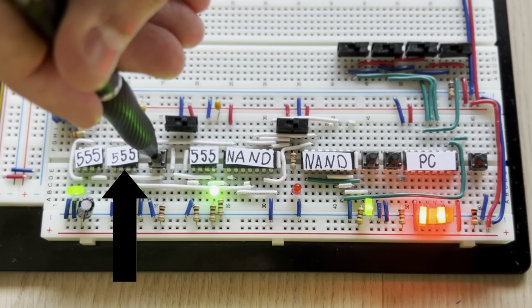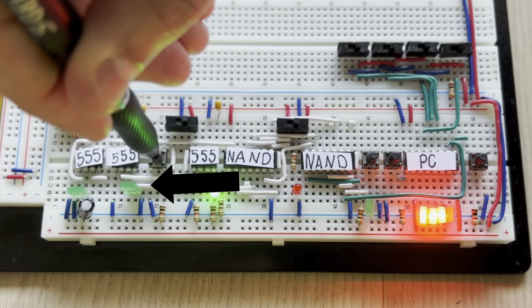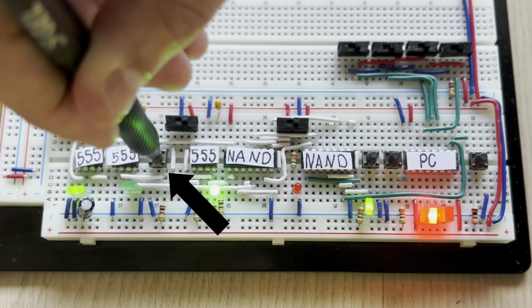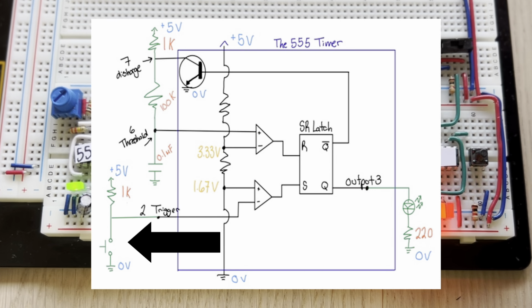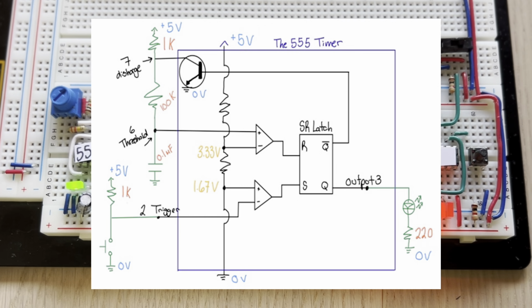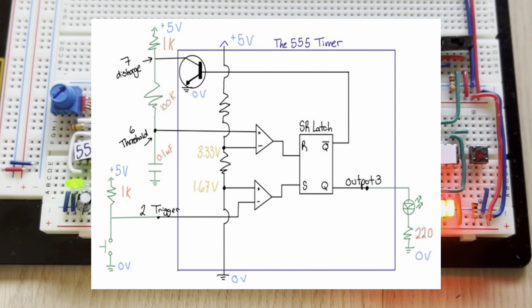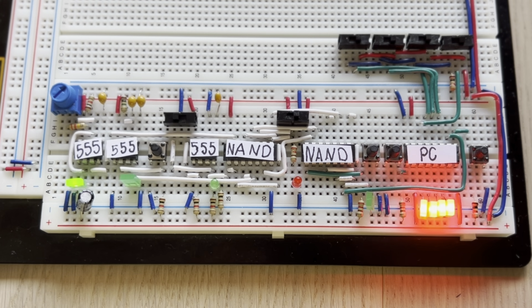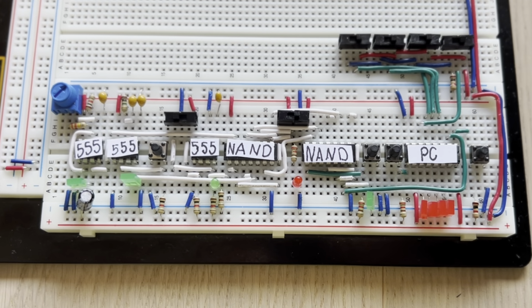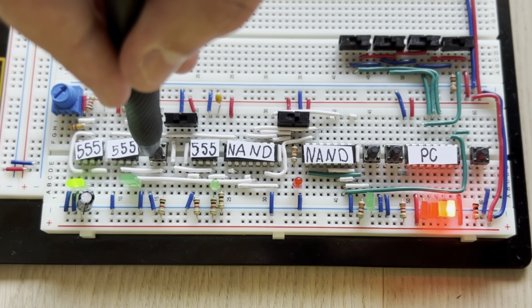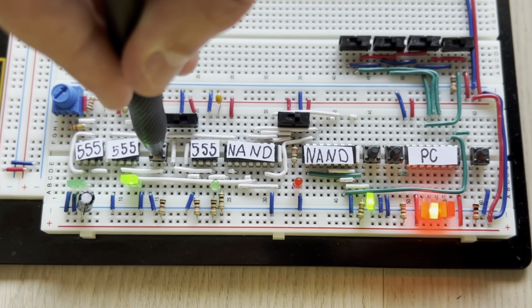Moving to the right, the monostable 555 generates a single output pulse when triggered by an external input, such as a button press. When the button is pressed, the timer's output switches to a high for a predetermined time before returning to low. The duration of this high state is controlled by external resistors and capacitors. This 555 setup acts as a debouncer as it removes any potential voltage leaks from the button when the 2 metal plates inside the button bounce off of each other repeatedly.